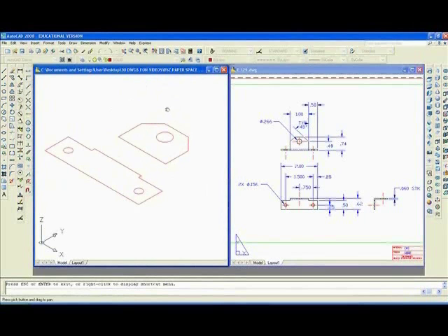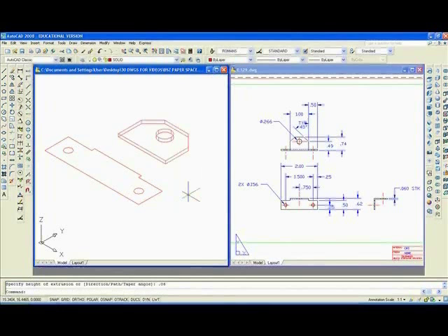Of course, we want to type EXT, enter to extrude. I'll try it again. EXT, yeah, it's showing up. Extrude the top piece, enter, 0.06, enter, and then subtract. You can type the word subtract or pick it there. Subtract from that, the whole, and repeat the command.